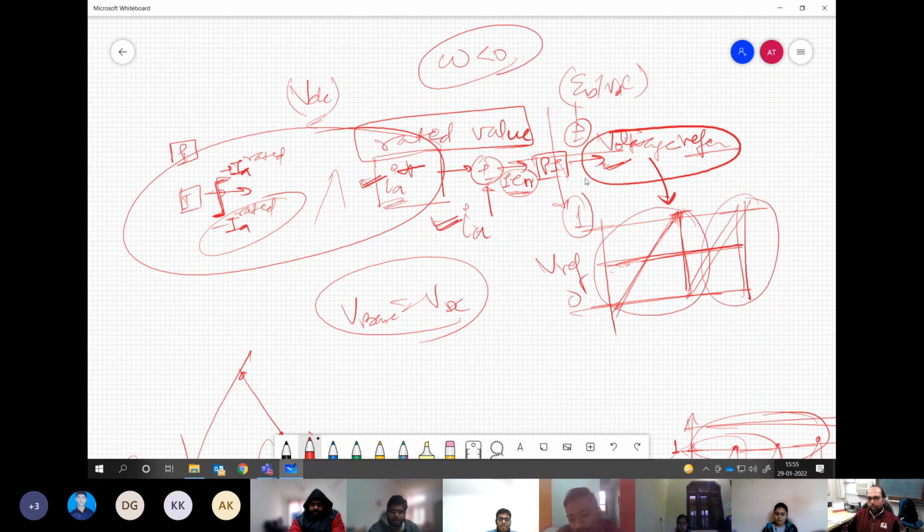So if you want to go for negative speed, do make arrangement in your converter for applying negative voltage as well. For a DC motor, with positive voltage you cannot achieve negative speed, which means the flux direction is fixed. You are not changing the flux direction. That's why we need to make arrangement in our converter if you want negative speed. Otherwise, anything up to the rated speed is possible.